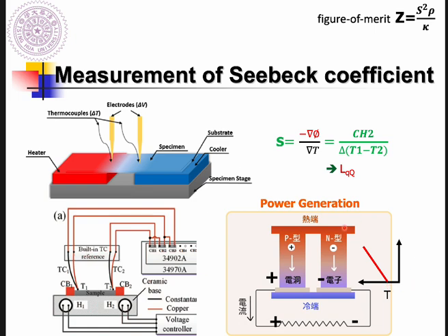And at the bottom, the hot side pushes the major carriers, which are electrons, to move to the bottom. So the electrical potential as a function of location goes from lower to higher. And here you have the electrical potential gradient divided by the temperature gradient, and it is negative. So the slope is positive, then you have a negative. So for N-type material, the Seebeck coefficient is negative.